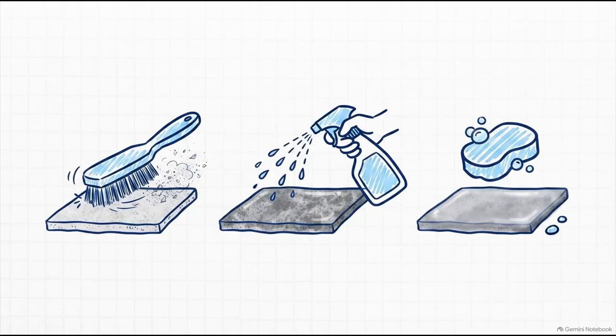But what happens when things don't go perfectly and the surface isn't fresh? Look, once a layer has hardened, you have to treat it exactly like existing concrete. You need to remove all the weak material, provide the required texture, and, crucially, bring it to a saturated surface dry, or SSD, condition. Doing this ensures the hardened surface doesn't just suck all the moisture right out of the fresh mix. It's the exact same bond logic we use for shooting against existing concrete walls.